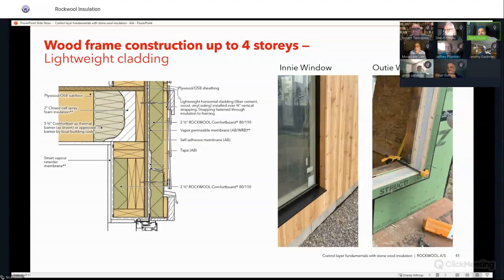So that's a big difference between the 1970s and what we do now, because some of the stuff we produce now is almost 100% stone, because we've learned lessons over the years that the old stuff doesn't hold up so well. It falls apart a little bit. Its workability is nowhere near what the new bats are today. So it's a big difference, stone fiber versus slag fiber.